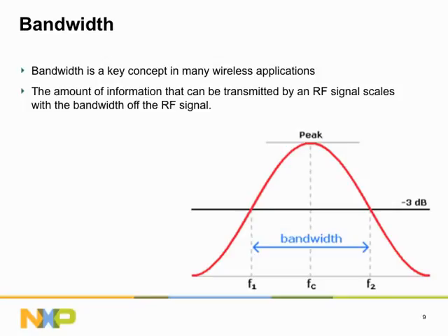The bandwidth of a signal can be considered as the width of the spectral chunk that is being covered by the signal or by the system. For instance, an FM radio can receive waves between 88 and 108 MHz. The car receiver then has a 20 MHz bandwidth. The FM wave per radio station itself has a certain bandwidth as well, which indicates how much information the wave can carry. So, your favorite FM station transmits a wave that is about 200 kHz wide.